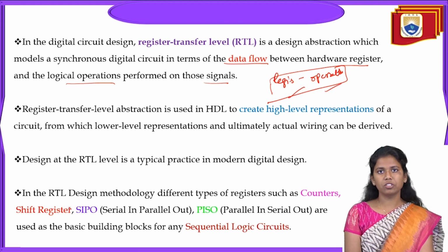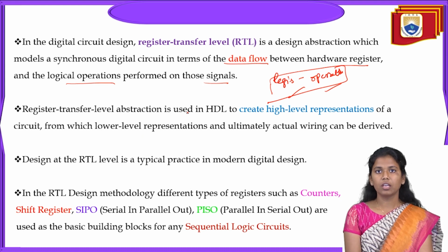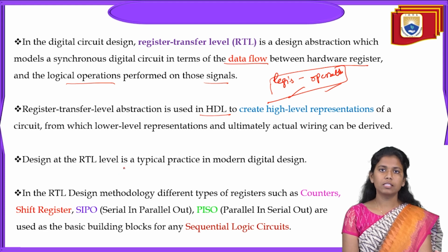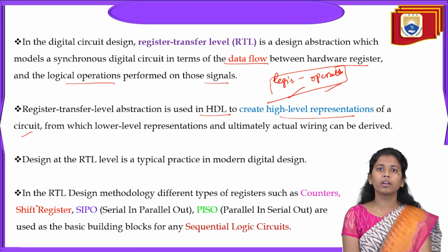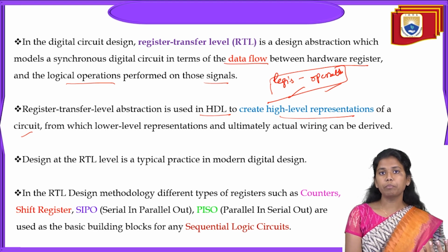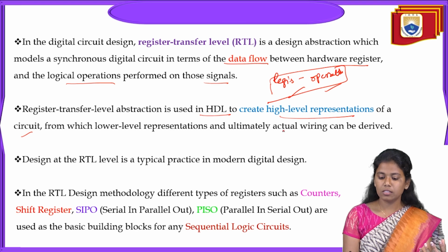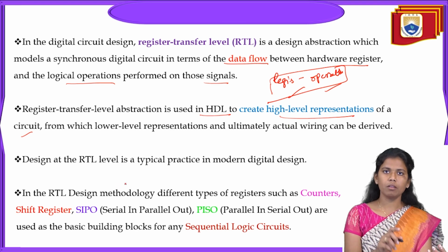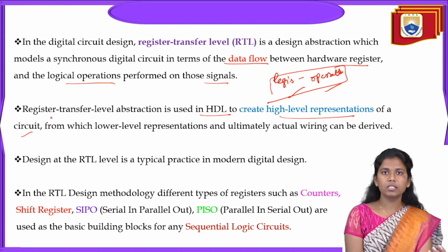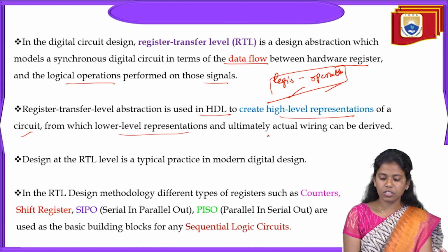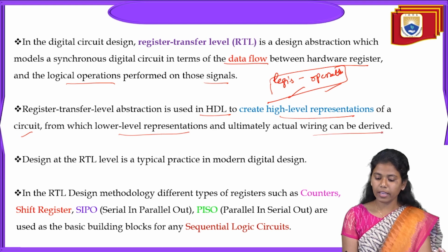And then RTL, register transfer level abstraction, is used in HDL. So in hardware description language, we use this level of abstraction to create high level representations of the circuit, from where low level representations and ultimately actual wiring can be derived.